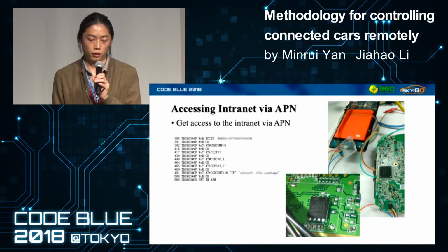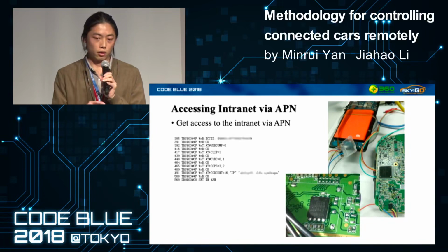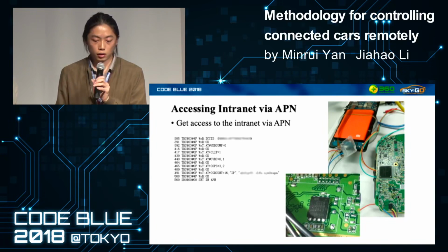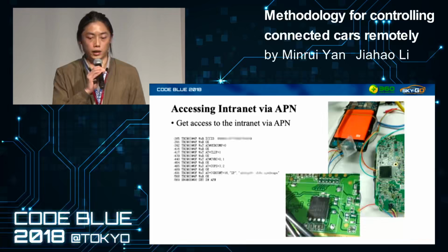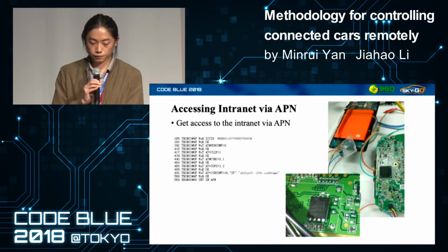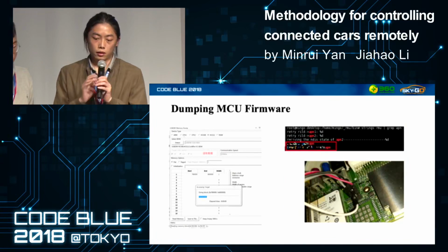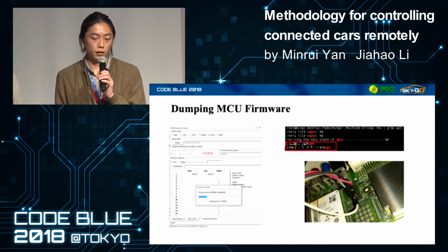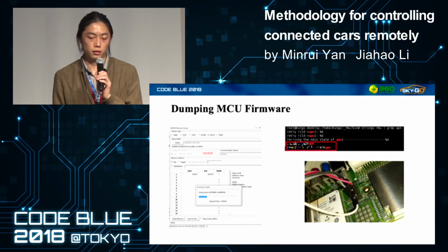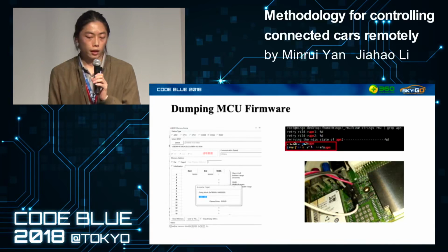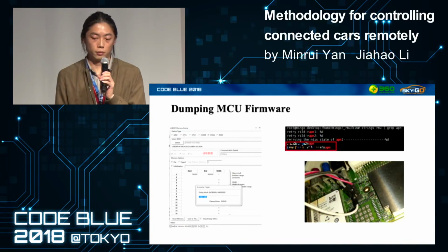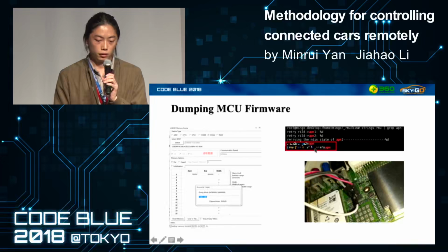We can jump wires from an eSIM to a phone SIM card slot, then configure the APN on the mobile phone. In this case, there is a chip made by Freescale. We found the debug port, which is not disabled. Then we need a more professional tool to dump the firmware. We can also get the APN from the MCU firmware. It's plain text in red, you can see.